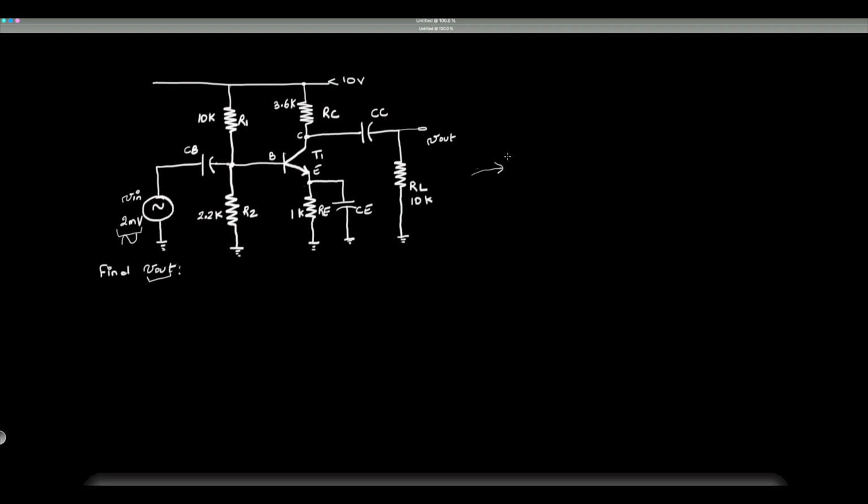For this circuit to work in AC, we're going to have to reconfigure it as the AC signal sees the circuit. So anything that is VCC, for example, right here, will be considered ground. In other words, this point right here will be the same as this point as a reference. So that means R1 and R2 are in parallel. So we're going to move in this direction, like this from left to right. Same thing here, from left to right, and evaluate the position of each element.